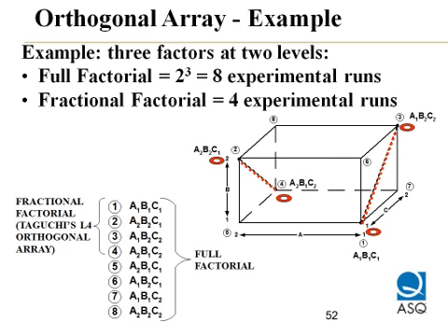And so we have the full factorial representing the 8 corners of that square, whereas a fractional factorial, Taguchi's L4 orthogonal array, for example, is the first 4 rows. Now, if you don't want to use the first 4, use the last 4. Either the 1 through 4 or 5 through 8 represents a fractional factorial of the full factorial.